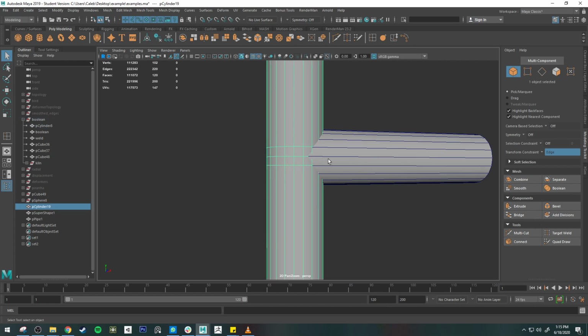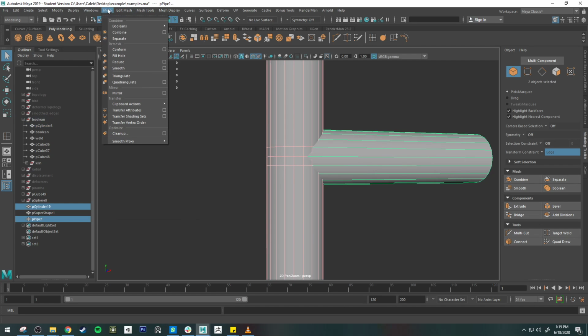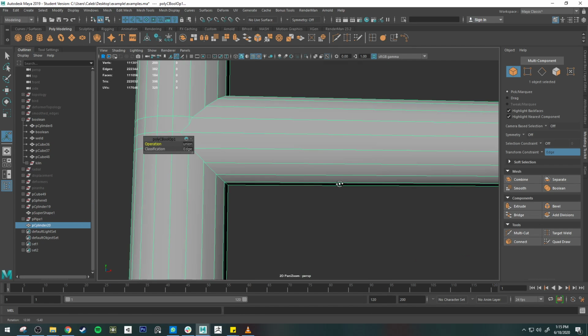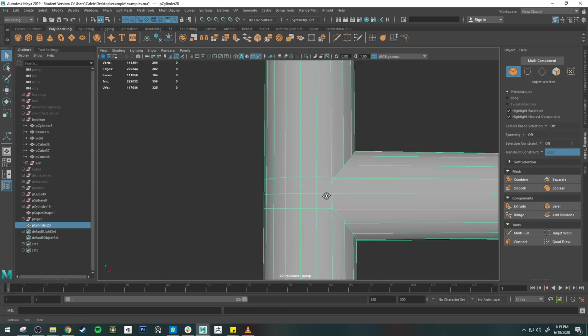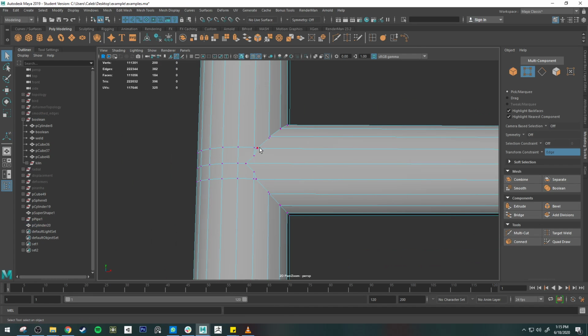And so now I'm going to weld these guys together. So we'll go Mesh, Mesh Booleans, Union. I keep calling it Weld, but it's called Union. And so now I need to start merging vertices, right? So I'm going to grab these vertices here, and merge into the center.